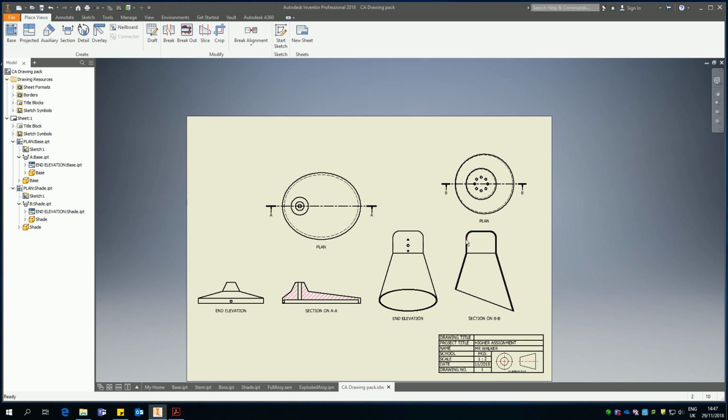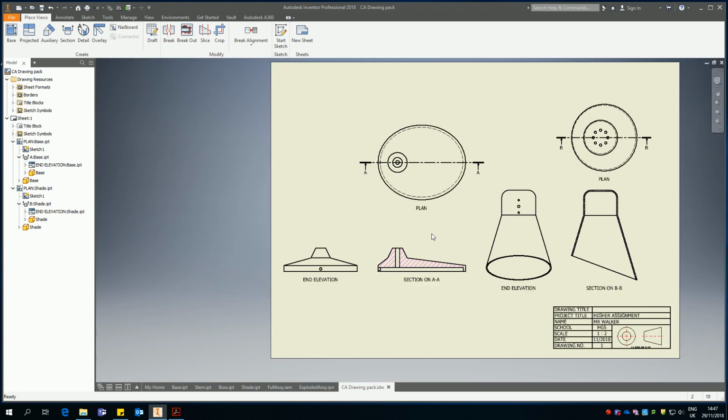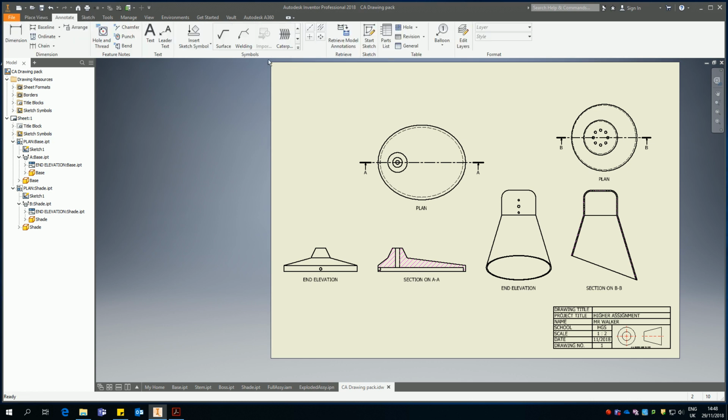So once I've set all this up, what I usually start with is center lines. Now this is going to be a bit of a pain of a drawing to create center lines for, for a multitude of different reasons. So there will need to be a lot of sketched information rather than actually just putting on layers.